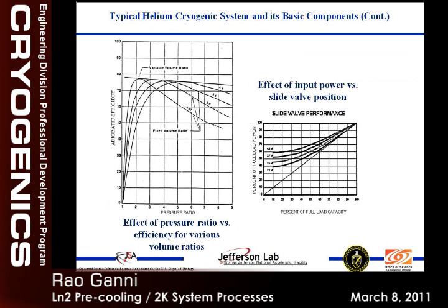So normally, given a process, they will tell you, tell me what your cycle is and we'll size it for you. That's a screw pump. They will say, for a given pressure ratio, here's your ideal built-in volume ratio, where the exhaust needs to open so that you have peak efficiency. Then they say, if you don't need the capacity, you can use the slide valve. This is linear. And even these are not optimistic. It doesn't work that way.